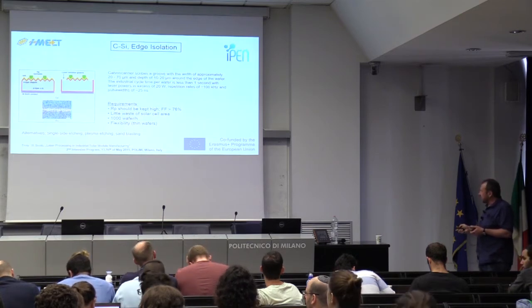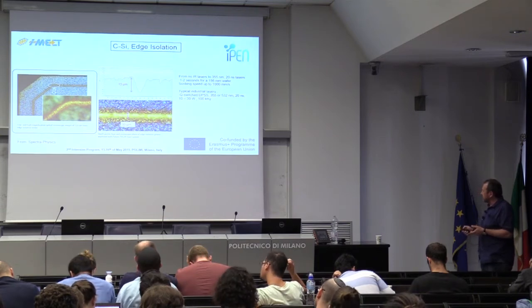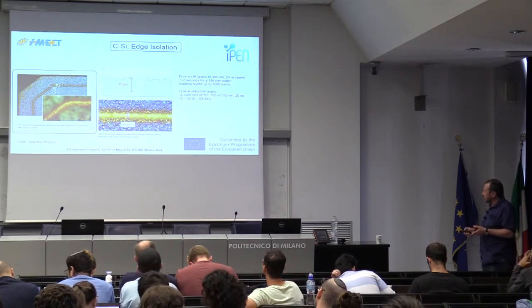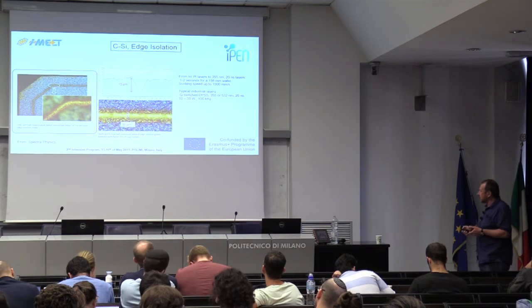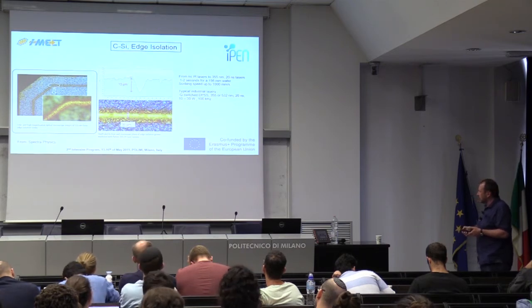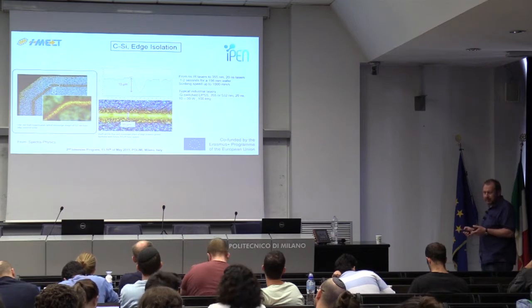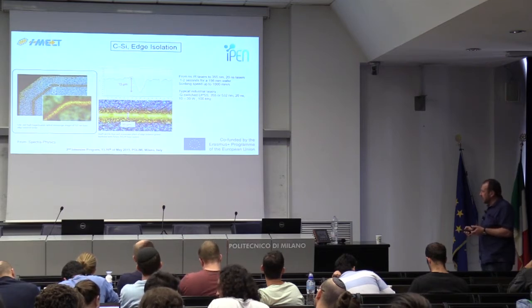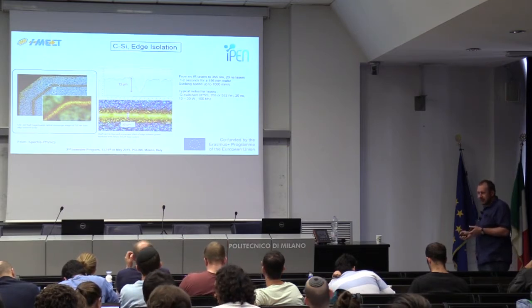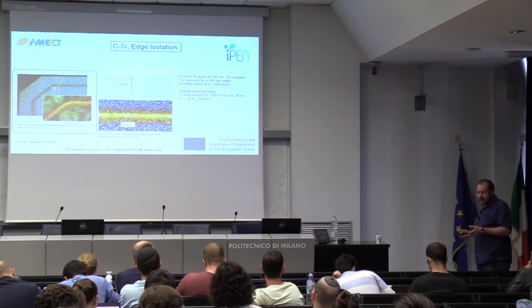Now here is another image of the groove made by an ultraviolet laser. How it looks like. The typical width and depth of the groove with this kind of laser may be a couple of tens or maybe 20 microns. If these grooves are made by infrared lasers, they tend to be something like 50, 60, 70, or 80 micrometers.